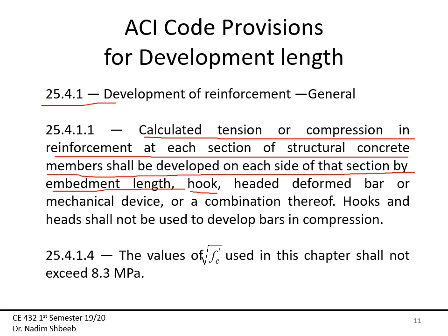Hooks, yes, sometimes when there's not enough space to put enough length, I can use a hook instead. We call it a headed deformed bar or a mechanical device or a combination thereof, which means anything I can use to get that development length in. We will not use hooks or heads in compression.